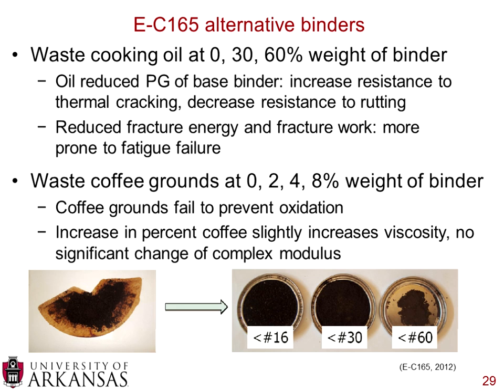And they found that also there's a reduction in the fracture energy, which contradicts the increase of resistance to thermal cracking in a way. Fracture energy is another way to try and quantify cracking, so there may be a discontinuity there. And also a concept called fracture work. And what this means is that they felt it's more prone to fatigue failure. So thermal cracking is one type of cracking, fatigue failure is a second type of cracking, and they found that using this oil reduces the fatigue cracking.